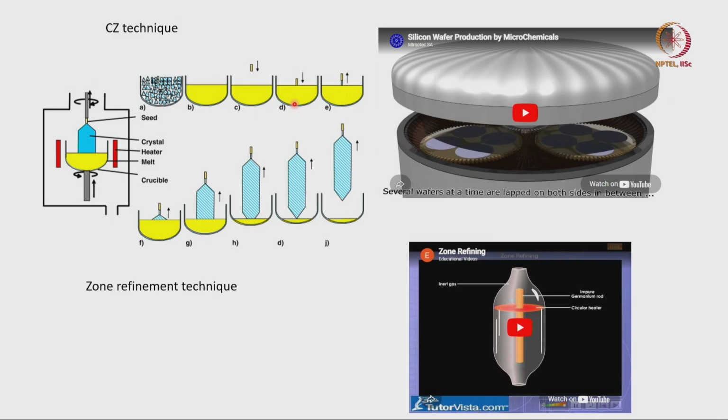Okay. Now what is happening? Just look at all the processes that are happening here. First, this is a very hot liquid, some 1000 degrees, 2000 degrees. I don't remember what the temperature is, but it is hot enough that silicon is a liquid here. Then I am putting in some cold material, which is a seed of silicon. Now this seed can also be polycrystalline, some kind of dirty silicon, but it is used to nucleate the silicon single crystal that is going to come up.